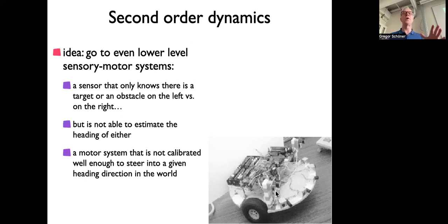There are two motors. These were originally toy plane servo motors, but we cut off the servo part. So they are unservoed velocity motors. That's kind of important because it means it's not guaranteed that they take on the velocity that you ask them to. And therefore, you will have to use the dynamical system, the planning part, as part of the control. So if they move more than you want, then the target moves, let's say, more than you want, and it would update the dynamics based on that. We plan as a form of control. And so the motors are below that.